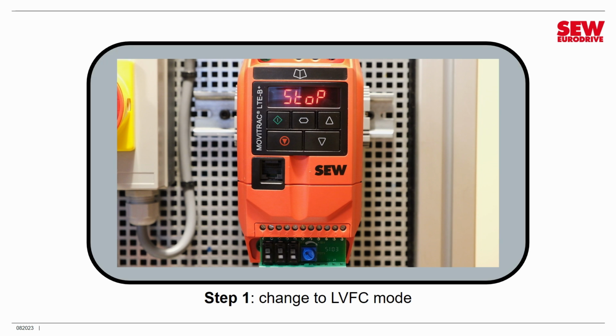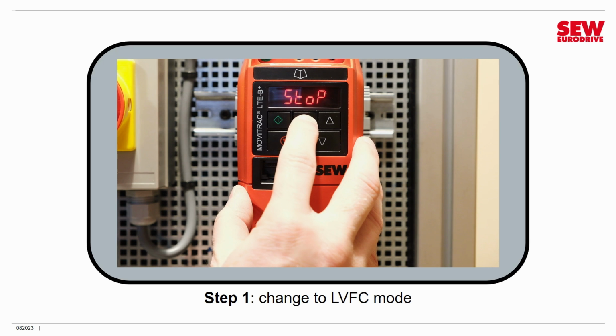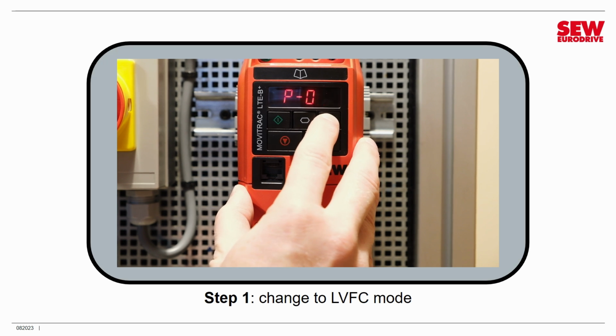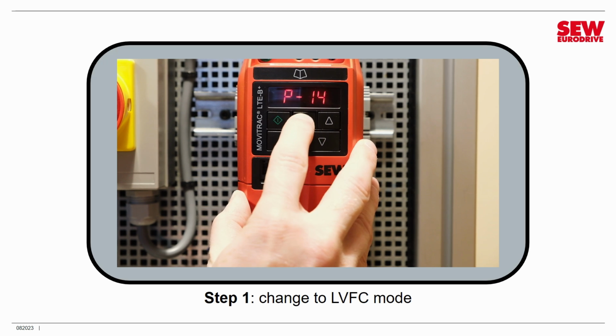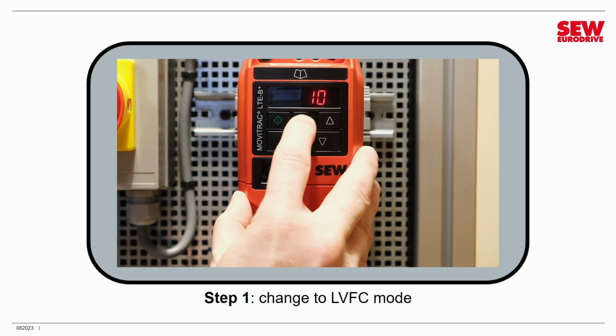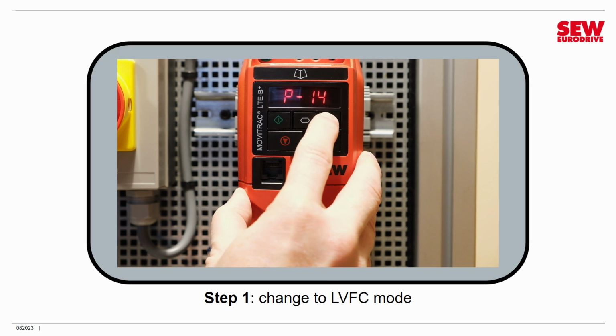All right, well, I hope that went well for you. I'm now going to demonstrate how to do this, so let's go ahead and do a quick demonstration. Now to change to LVFC mode, we need to unlock the extended parameters. So what I'm going to do first is hold down the navigate button a few seconds to enter parameter edit mode. Now I'm going to navigate to parameter 14, and I'm going to change that to 101. So I hit navigate, I set it to 101, and I hit navigate again. That unlocks my extended parameters.